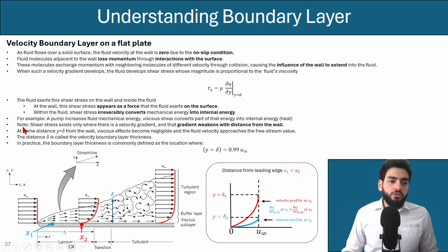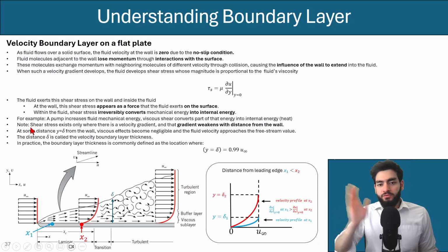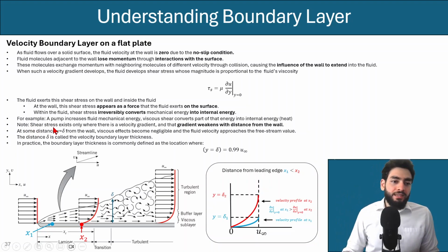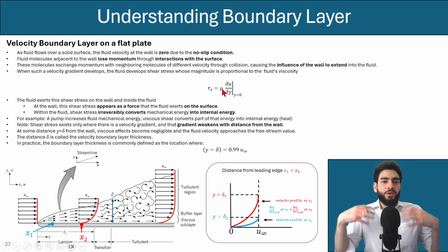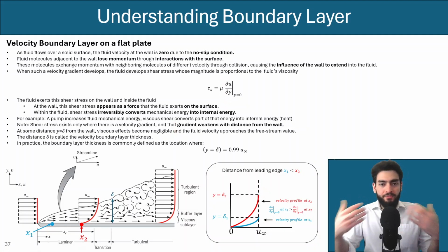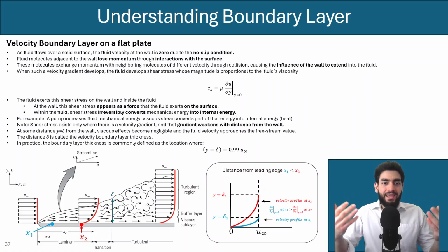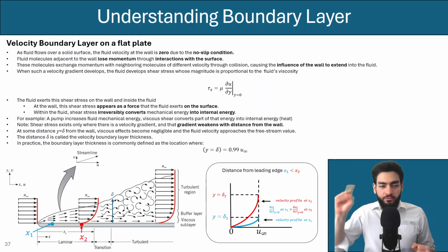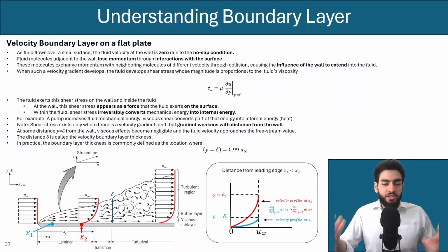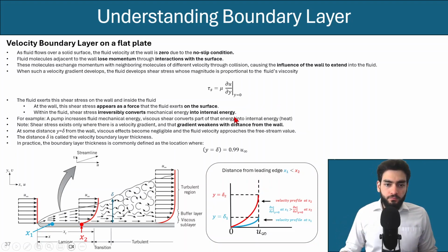Also, I just want you to note, because now we've sidetracked a little bit, that the shear stress exists only because of the velocity gradient. And so for instance, when you have a pump that you have sized, what the pump does is that it allows you to maintain that velocity gradient, and that velocity gradient then produces that shear stress that converts some of that mechanical energy into internal energy that is absorbed by the fluid.